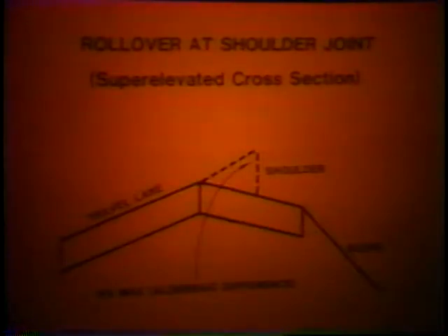Severe increase in cross slope between the travel lane and the shoulder produces a ridge or barn roof profile. Vehicles moving from the travel lane to the shoulder experience a sudden pitch-over motion. In wet weather, skidding can occur when the driver oversteers to correct the travel direction. The cross-slope differential should not exceed 8% in super-elevated cross-sections to minimize the pitch-over effect. Smaller vehicles are even more susceptible to pitch-over.